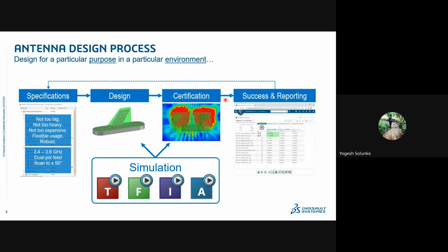Once we have designed the antenna, we see what its scattering parameters are and how much bandwidth has been achieved. If it is a MIMO, then we see how much coupling, cross coupling, there is. Once we go into the 3D side, we can see its radiation pattern and polar plots, co and cross polarizations and all.